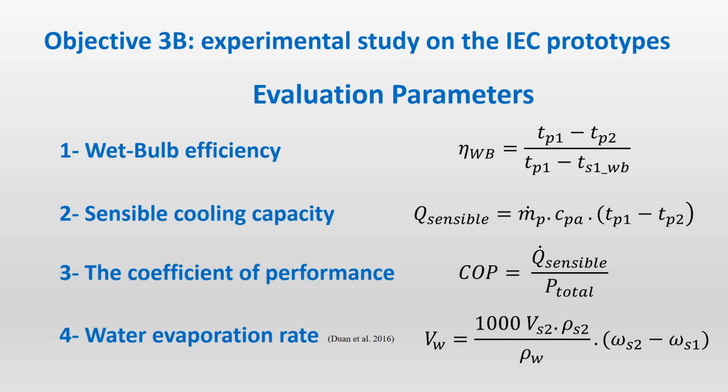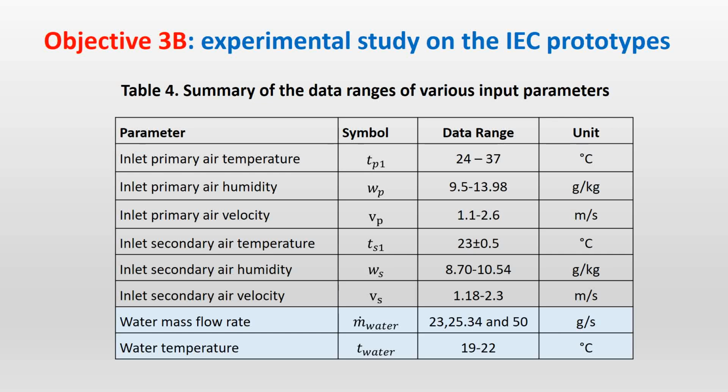The results for all these three have already been published, but this part hasn't been published yet because I added it after we did the submission of the publication. Now, this point is very important because water is a precious item. So each time we work on something evaporating the water, we're going to lose some water. So we have to make this sensitivity test. The input is going to be almost the same, but we just added these two parameters, which are the water mass flow rate and the water temperature. This is not actually a control thing. That's because the water, as it evaporates, is losing temperature, and then we have to add water to the sump to replace the evaporated water.